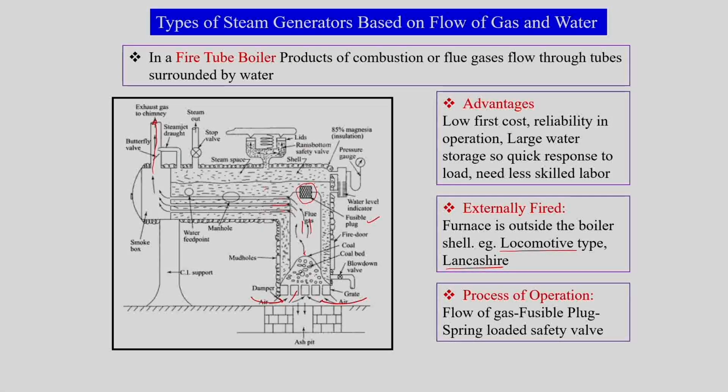So, this fusible plug is a control unit for the temperature of the water or steam supplied. Then there is the pressure safety valve. This is a spring based mechanical safety valve where the spring pressure will be adjusted such that the force of the steam pressure and the spring get balanced and the valve remains closed.